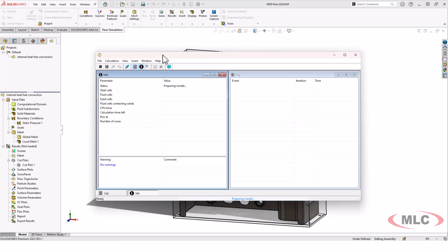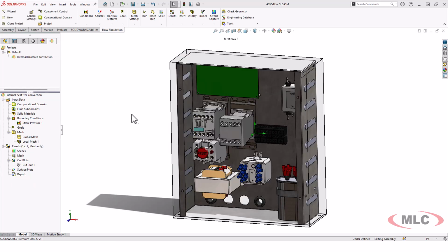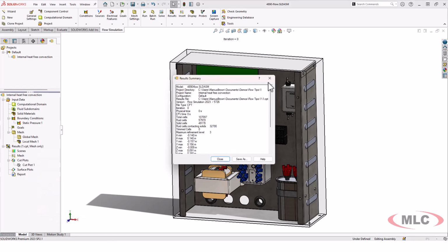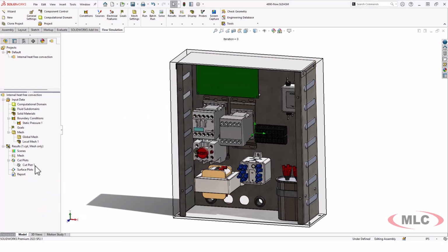and updates. We got a lot less solid refinement level, but we got a higher refinement level only on the lids. And this one's going to solve quite a bit faster because it's not going through and having to do refinements on every single face. And it flashed up there real fast, but basically instead of 600,000, now I'm at close to 100,000.